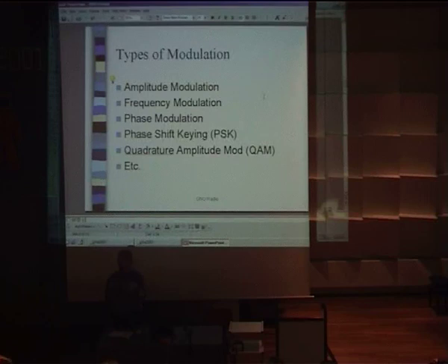And then it comes down to whether it's a continuous signal that's being modulated, or, for example, in our cell phones today, they're actually burst modes, usually time division multiple access. So what happens is you have a little tiny window where they transmit to your phone, and your phone transmits back, and you may be sharing it with 8 other people at the same frequency. So there are some tricks in that: I've got to sync up with the signal, and I've only got about a millisecond to establish synchronization before the signal's done flying.